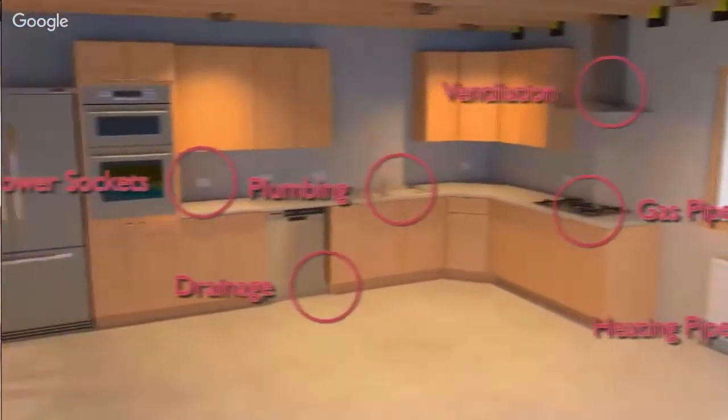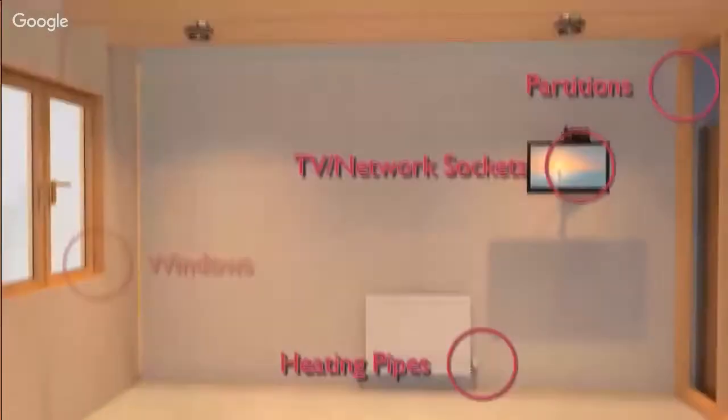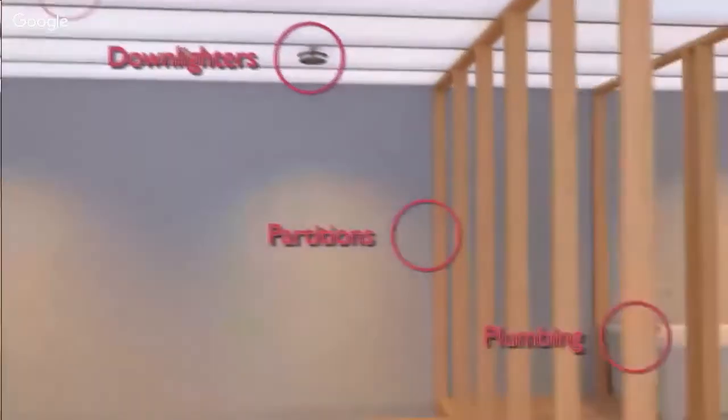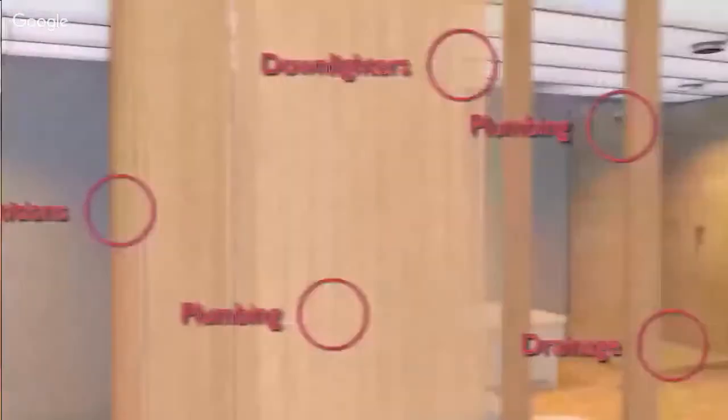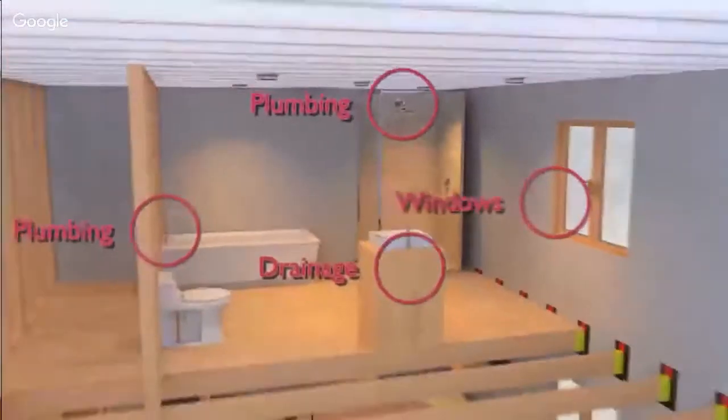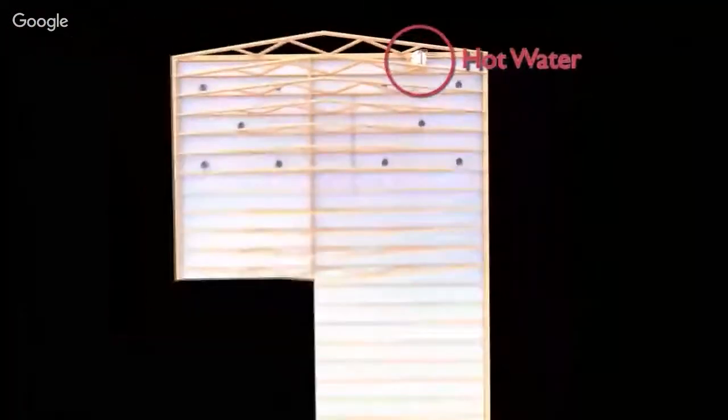Each of these seals represents a potential point of failure for the internal airtight layer. Now, the issue with that is that it may not be discovered until the membrane is covered by internal decorative finishes. And that makes remediation complex and it makes it expensive. But most importantly, failure to meet the designed air leakage rates can have a major effect on the energy performance of the building.